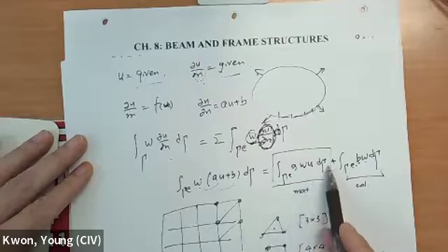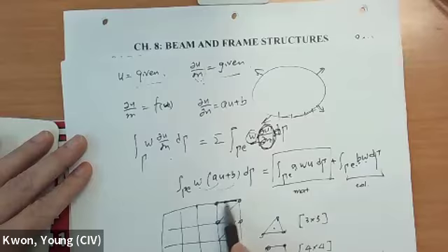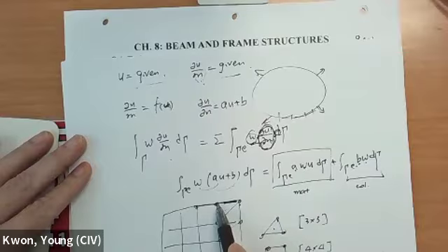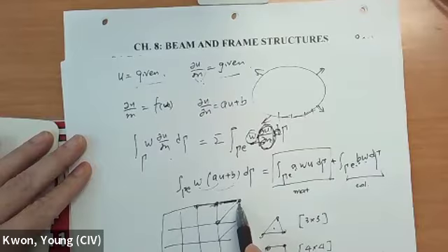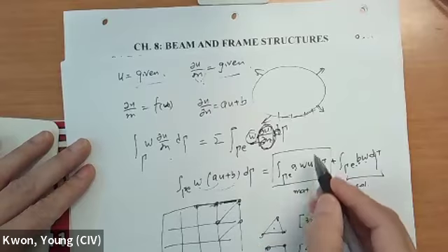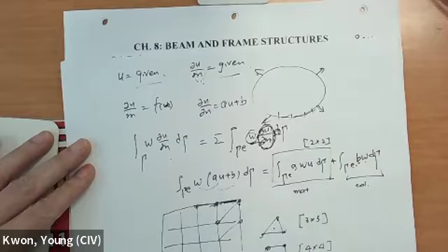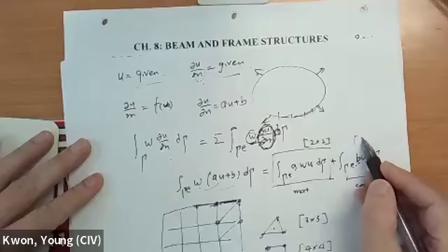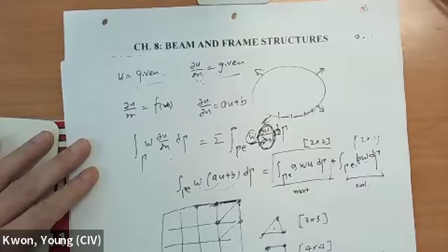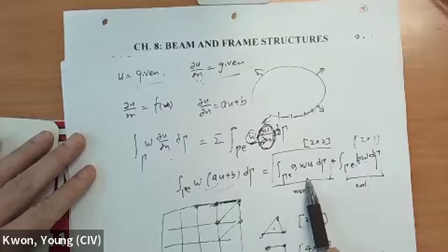But this boundary integral is going to be along the boundary, either this one or that one or that one. So along the boundary, each element has only 2 degrees of freedom. So this is going to be a 2 by 2 matrix, and this is also a 2 by 1 column vector. So that's the key point in your first project.